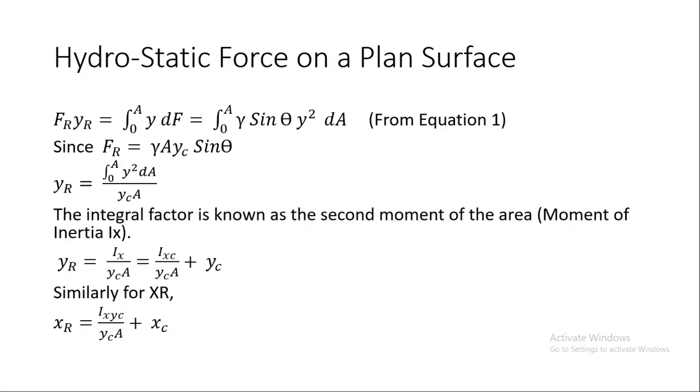So by knowing XR and YR, you can actually understand where exactly the resultant force is present and applying force. And if we talk about liquids, definitely its direction will be perpendicular to the solid boundary, so there is no need to determine the angle of the resultant force.